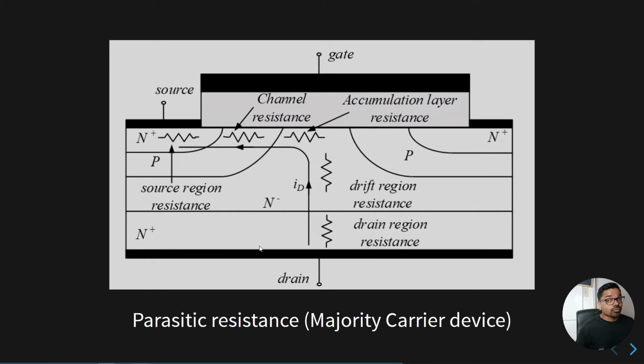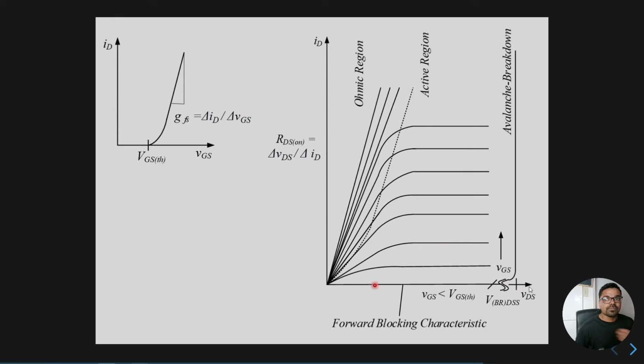So on the right axis we have voltage of drain to source, and that'll be the value of your MOSFET, your typical rating of your MOSFET. The MOSFET that I've just showed you earlier in this video was a 30 volt MOSFET. It was rated at 30 volts. So if you go beyond 30 volts, you're going to have an avalanche breakdown and you'll burn your MOSFET. So you don't want to go beyond the typical rating capacity.